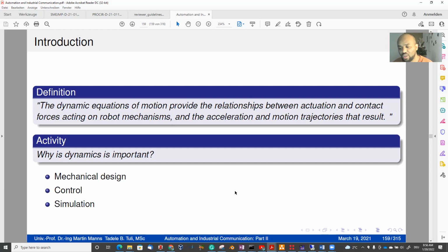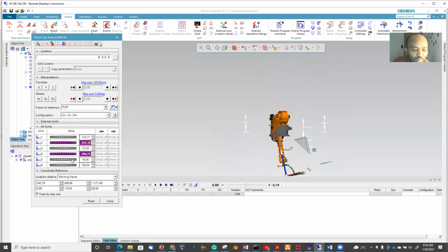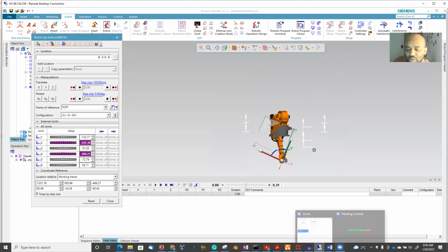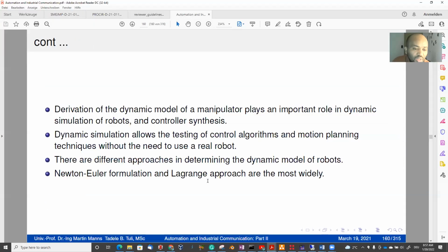So if you use a simulation in the offline environment, first check everything and then finally deploy your program. That's why it is easier. That's why we use simulations before we go to everything. You program some operations, check which angle is appropriate, which paths, everything, then you study the cycle time, download the code, and finally deploy it. That way it will simplify your life.